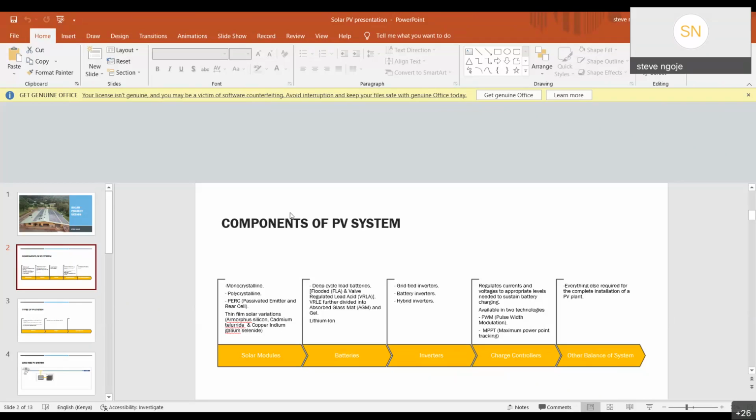But of course, there are instances when you will consider PWM. Most of that is based on finances. When you have to do that, it's probably going to be because of the price difference. MPPT charge controllers are a little bit more expensive. And also, if you happen to come by small modules that are rated at 12, 24, or whichever voltage level your battery system is.